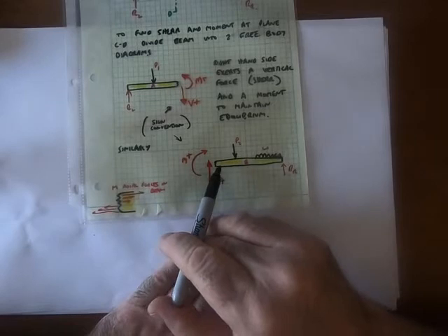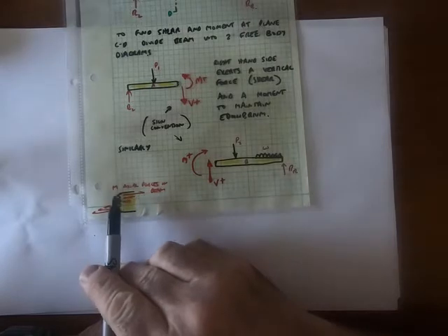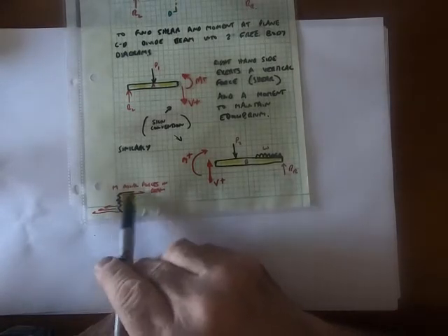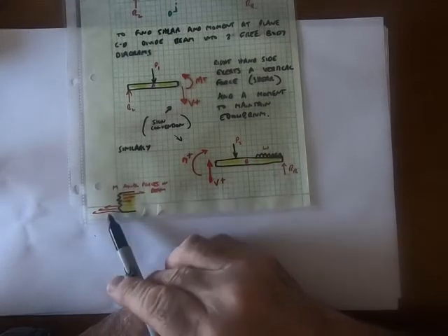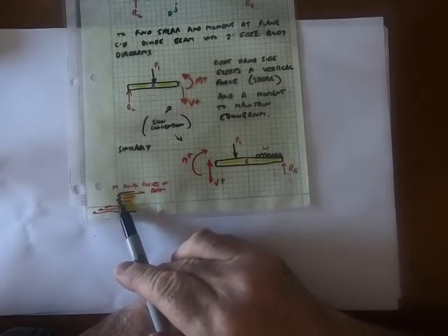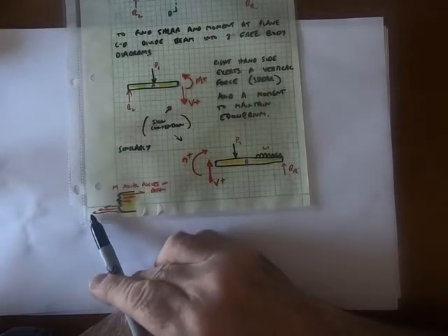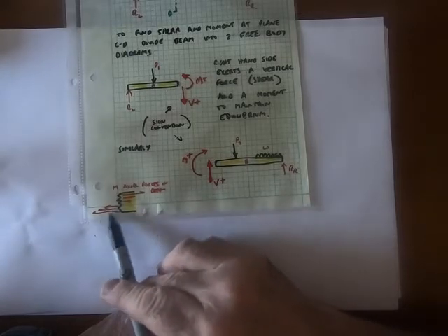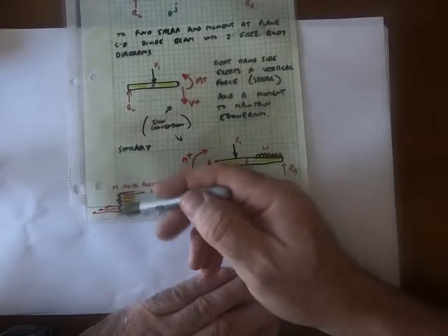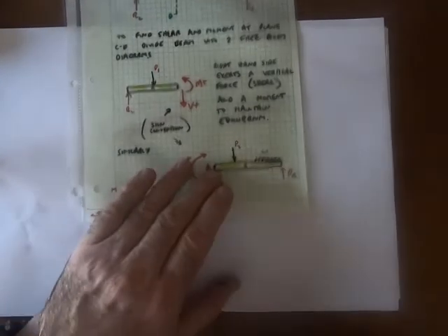So for this one here, if we were to provide that moment shown, that M plus, we would need forces acting in two different directions to give us the couple. Those forces would be a max at the surface of the material, and then they would diminish slowly to zero, not necessarily in the mid-axis, but what we call the neutral axis. And these stresses over these areas are what we call the shear stresses due to the bending moment. That's what's actually happening in the material. So we have these normal stresses, they're called, and then we have the shear stresses along the surface, and the two of those combine, and we'll talk about those more later in the course.